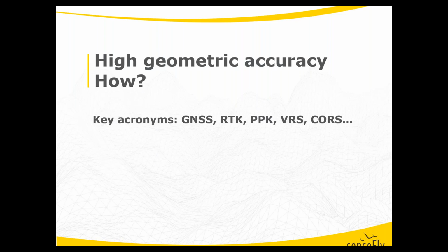So GNSS is just a more general word for GPS. But anything you know about GPS is valid in GNSS. RTK and PPK, it's an important point already mentioned in the description of the EB+. The K is for kinematic, because everything that we will measure will be during the flight while the aircraft is moving. So everything will be kinematic.